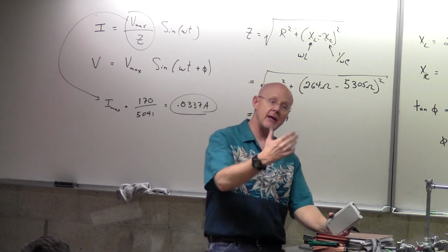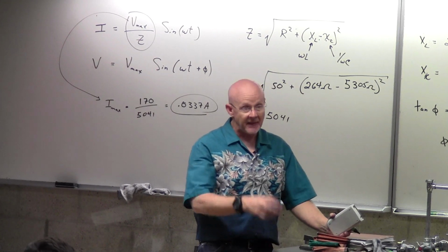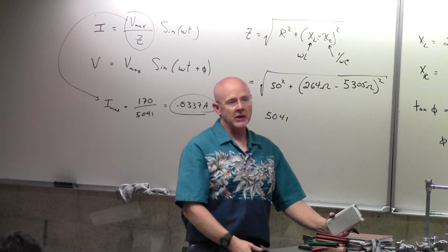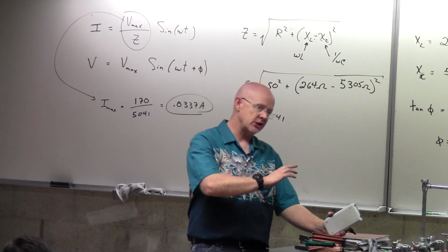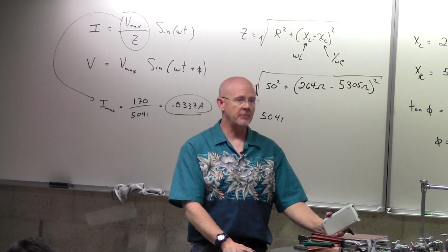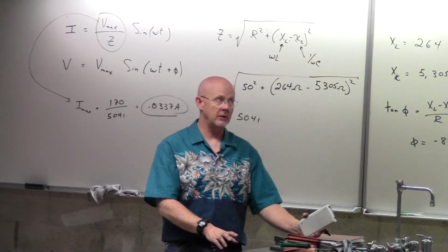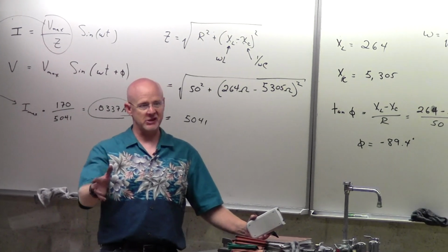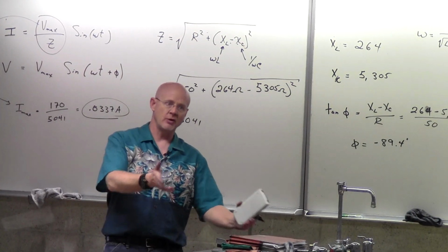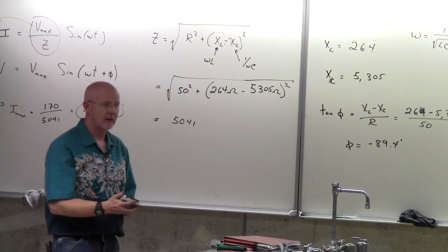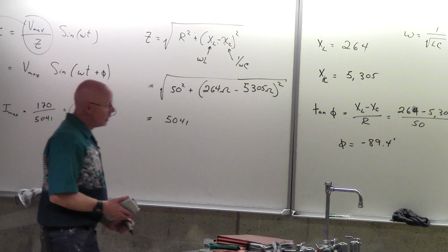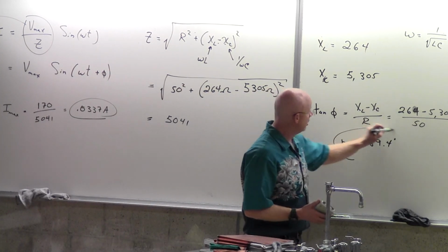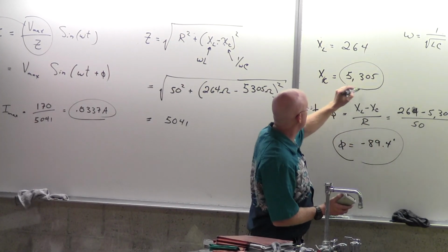Any higher than that, it acts more like the inductor. And the higher it gets, the more the inductor dominates. So at really high frequencies, you could ignore the capacitor and resistor, and at low frequencies, you could ignore the resistor and the inductor. But in this case, we got them both, and you can see it's just so highly dominated.